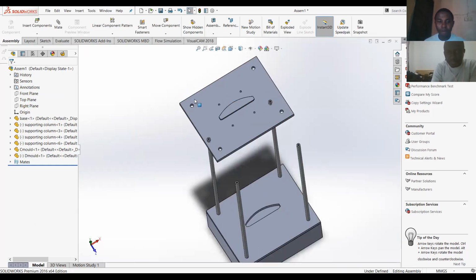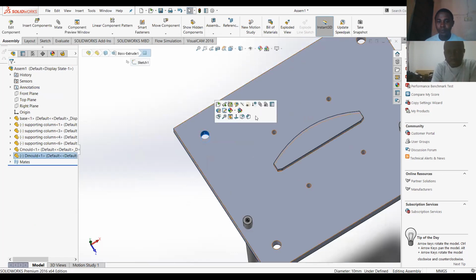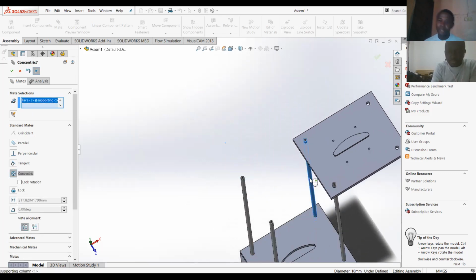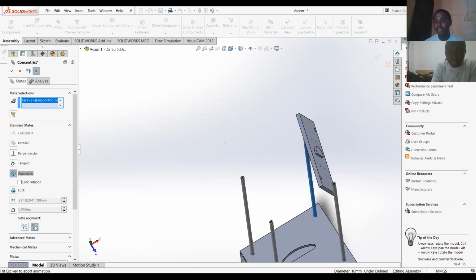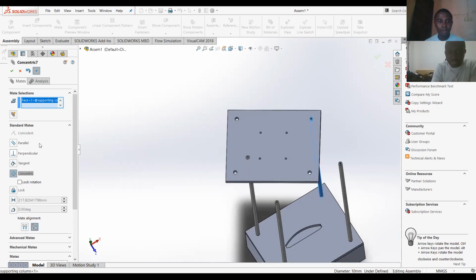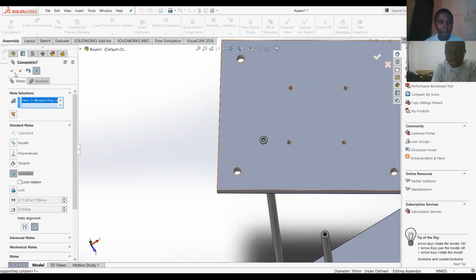So what I will do is to do the concentric mates. I think that this hole should correspond with this place. Then flip upside down. So there are two things here. Just follow my cursor, flip mate. I'll just change alignment like that. It knows that it needs to turn it upside down. Then for the second one, I'll mark the mate, I'm done. Do the second hole.